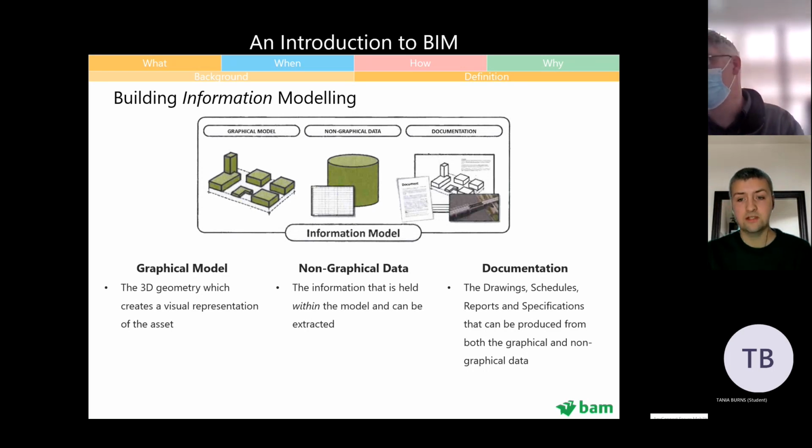So when they make a change on, let's just say, an elevation, they decide to move the window over a wee bit, they have to then open the floor plan drawing separately to move the window to match the same location. If they forget, the two drawings contradict each other. This can't happen when you're using BIM software, because it all talks to each other. If you move something in one view, it's automatically moved in the other view, including in the model itself and in all your drawings.